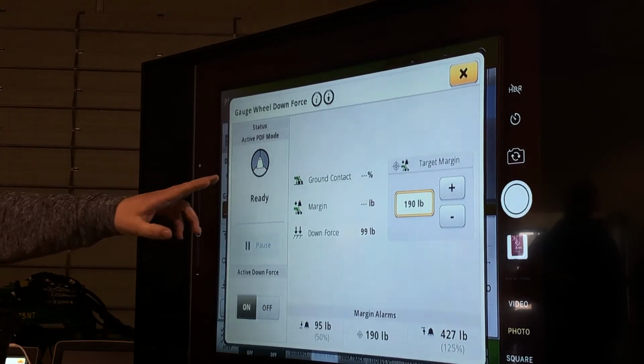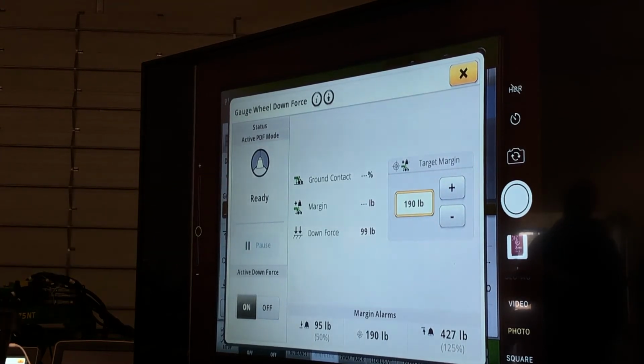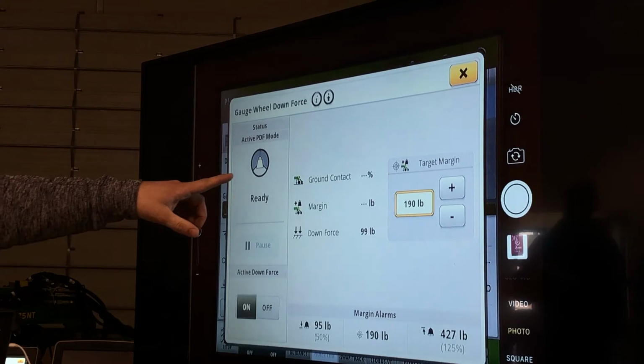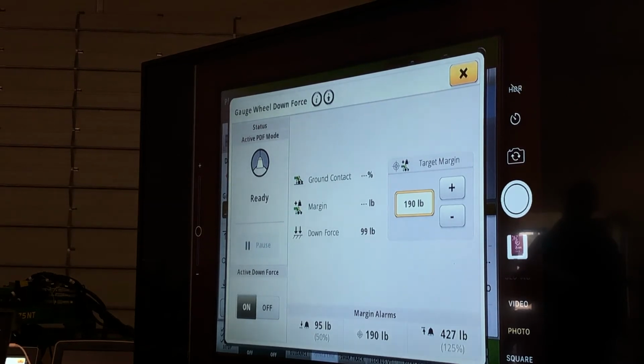This bottom one, I remember the easiest, but it's the planter lower. When we lower the planter, that is going to fill in. We did have an issue with a row unit height switch not getting power, and so we weren't able to fill in that bottom piece of the pie. Once again, that's how we can use it as a diagnostic tool, even before we go to the field. So once we get all three, go ahead.